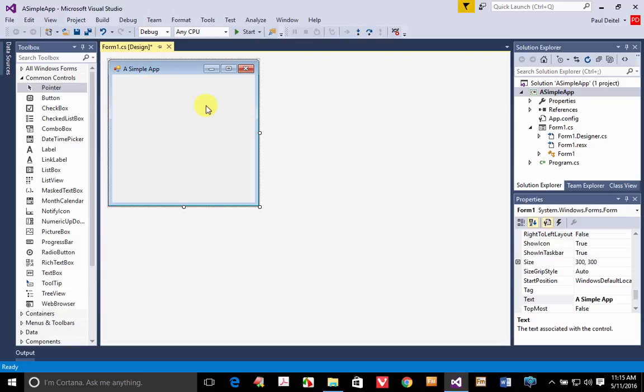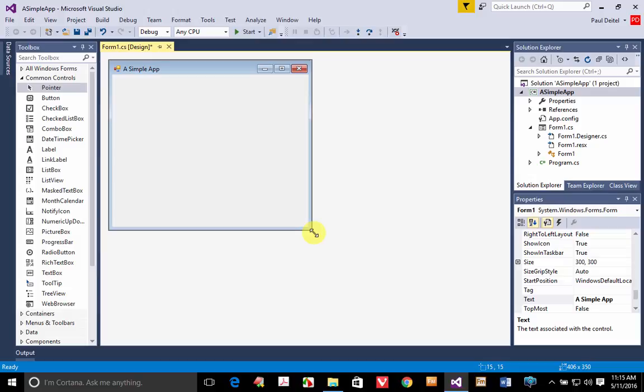And we can do that a couple of different ways. First of all, you'll notice that there are sizing handles that you can use to stretch the window horizontally, vertically, or diagonally. And in our case, we grabbed this handle and just started dragging down to the right. And you'll notice down here it's showing you the current width and height. Now, again, 400 by 360 pixels, so you can see I can kind of get it close, and if I drag slowly enough I might be able to get right onto the number.